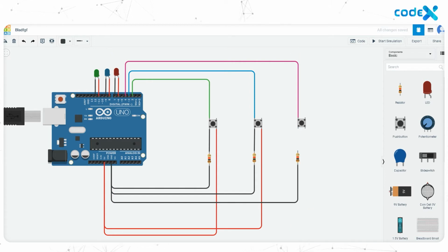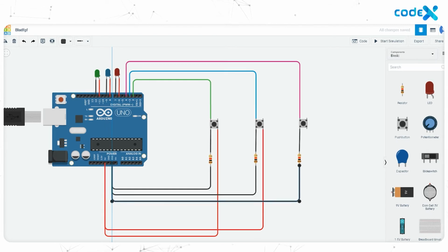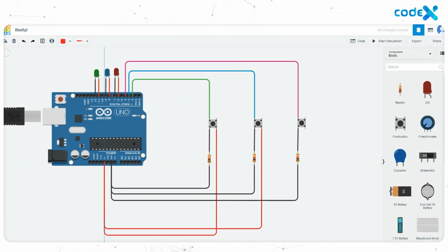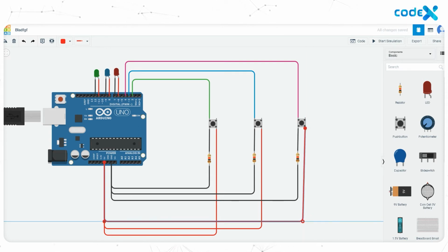And from the other end, connect it to the 1A terminal of the third push button switch. Then adjust the Y connection a little. Now change the Y color to red and connect the 5V pin to the 2A terminal of the third push button switch. Then adjust the wire. So we have finished the connections.